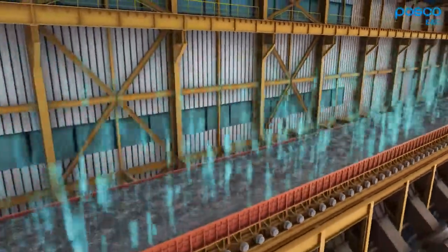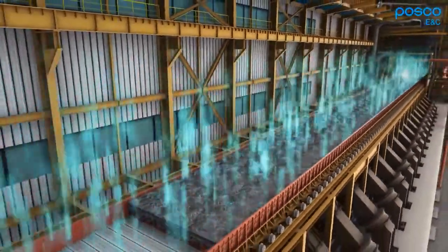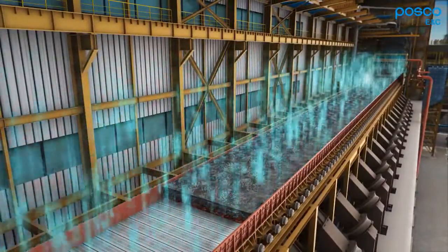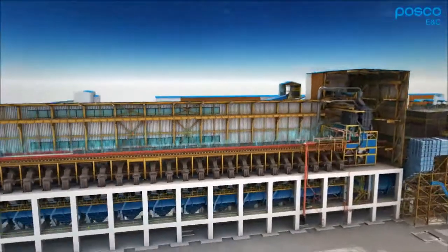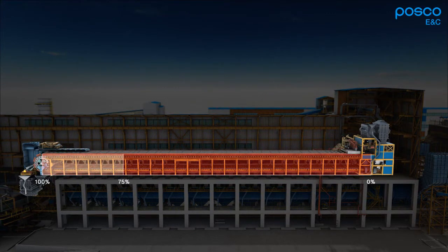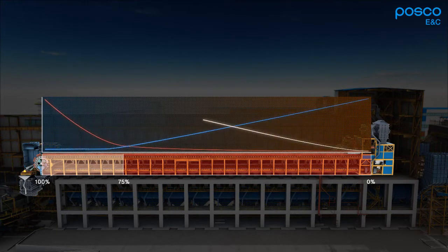While this process is in progress, the pallet continues to move the materials forward, which makes continuous operation possible. And during the whole sintering process, the exhaust gas temperature is measured at the main control room. At the moment when more than 70% of the sintering process progresses, the exhaust gas temperature increases rapidly, which means all the moisture in the materials evaporates and the sintering process is completed.